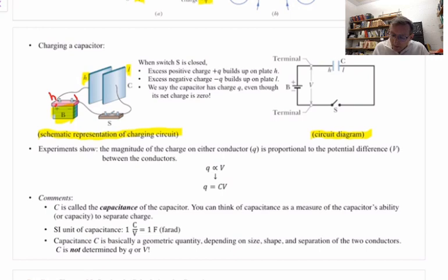All right, now, this shape here represents the battery. And it's got a short line and a long line. And the longer line is the high potential side, and the shorter line is the low potential side. They're labeled plus minus. And then it represents the actual terminals of the battery, there and there. And the battery's job is to produce a certain potential difference across its two terminals. And that's what this V here represents. The potential difference across the two terminals of the battery, produced by the internal chemistry of the battery itself.